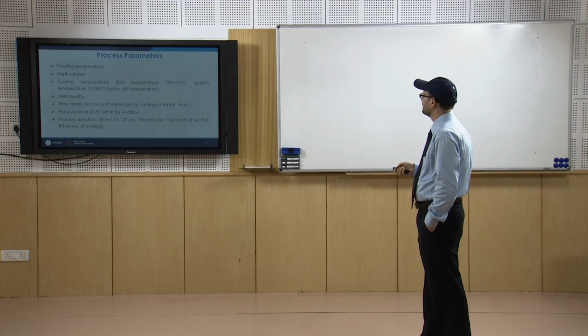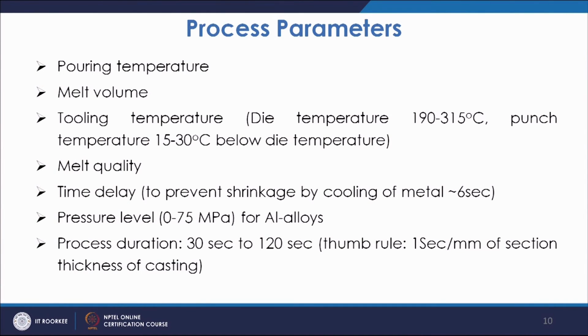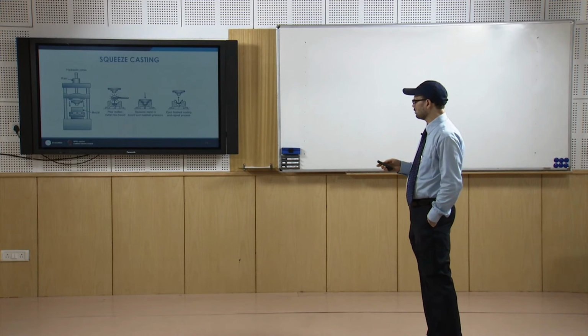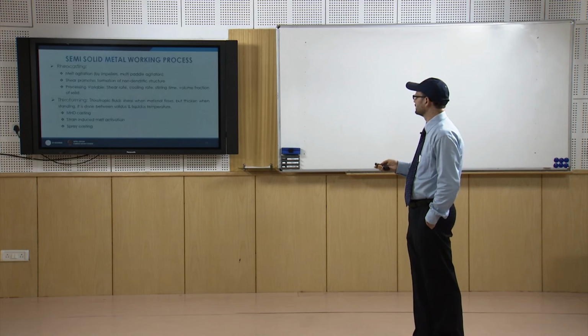the duration, that is normally 30 seconds to 120 seconds. The thumb rule is 1 second per mm of section thickness of casting. So, that is the duration of the process. So, this is how we have seen that this is squeeze casting.